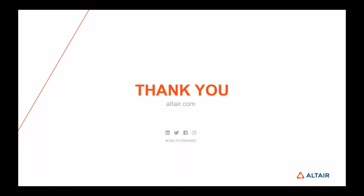The GEM database is already a test performed with these parameters with a given result, and it has a wider reach. It has, I think, around 60 or 70,000 different material models that you can choose from. The breakage material library that we have is more reduced, as I said, around 20, and you can definitely use the parameters there. They are good parameters that have been taken from Professor Tavares' group. But I would say typically better to use them as a starting point for adjusting them further yourself later on.